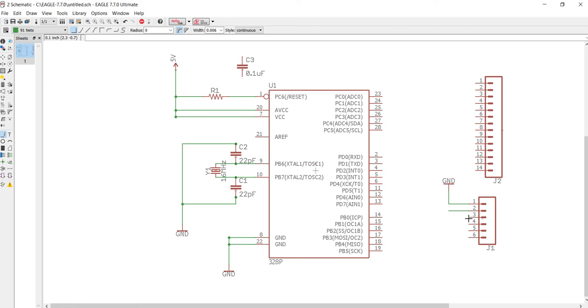The next line is VCC. And the CTS line, we're actually not going to connect that to anything. We're going to just do RX, power, and ground. So in this situation, we will actually be taking power from the FTDI chip to power this Arduino.